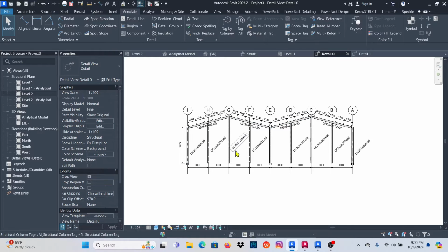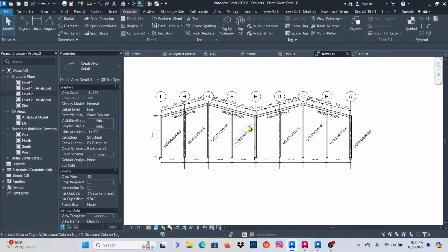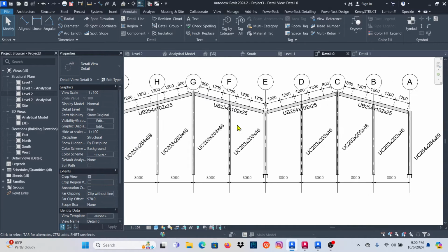So in Revit, you can continue adding all the details and complete everything within here, except that for the fabrication drawings, the main parts, the single parts, and bill of materials, it's not automated, it's manual. So that's why we want to use Advance Steel.